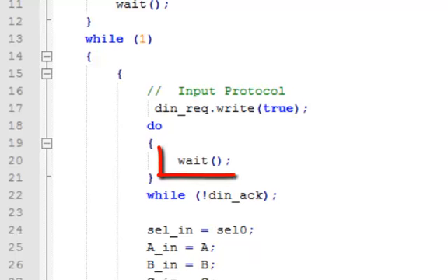In this portion of the code, you will see a number of wait statements. This means suspend this thread until the next active clock edge. This piece of code shows how we would represent the always @(posedge clock) functionality in the Verilog code.